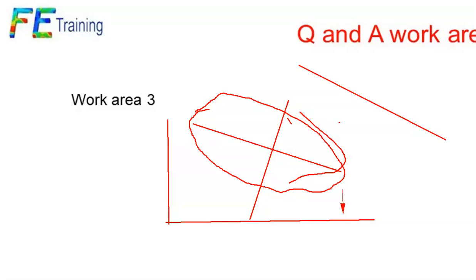If we look at the stress vector through the history of the cycle, the stress is swinging around all over the place. So there it's generally going to be used in a general combined stress state, so we kind of cheat. There are more, it's called multi-axial analysis. That's proportional. Full multi-axial is way beyond the scope of the half an hour here. It's probably going to be a PhD thesis in its own right.